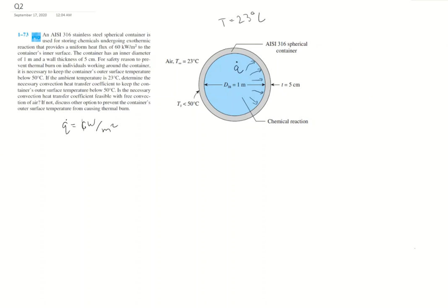And we know that heat's going to be emitted through the air. And sorry, we know that we need the surface to be 50 degrees Celsius. That's the surface temperature. And the way that this transfers to the air, it's going to depend on this difference of temperature here and temperature here, but it also depends on h, which is the heat transfer coefficient.